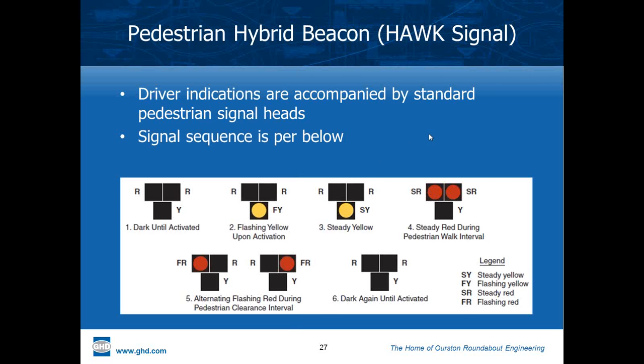I guess the reasoning is, we understand flashing yellow, but that's not sufficient for regulatory right-of-way. So we introduce the red. But if it goes to a solid red, and the red is there for the whole phase, then we don't provide any passage of traffic when the pedestrian has cleared the crosswalk. So the flashing red says to the driver, proceed only when it's safe, when the crossing's not occupied.